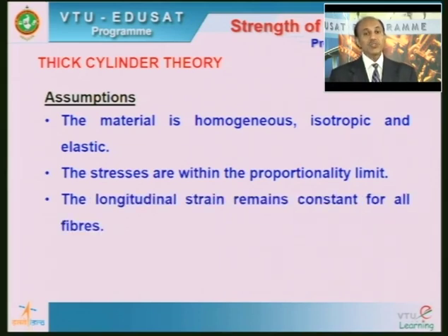And the longitudinal strain remains constant for all the fibers. Please understand, imagine that the thick cylinder is made of a number of independent, individual fibers. So, the amount of strain each and every fiber along the length experiences is the same, and hence even the stresses will also be the same in each and every longitudinal fiber. So, this assumption we are going to pick up and then use in the derivation.